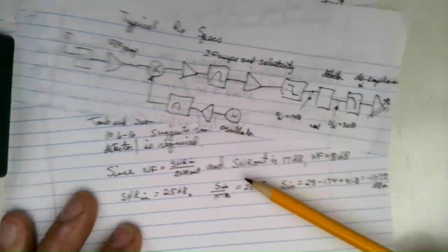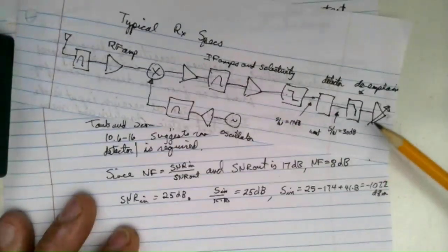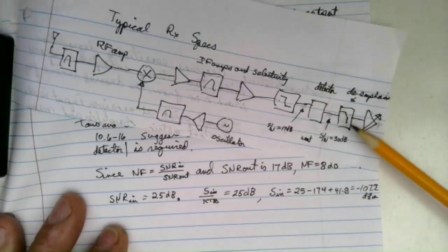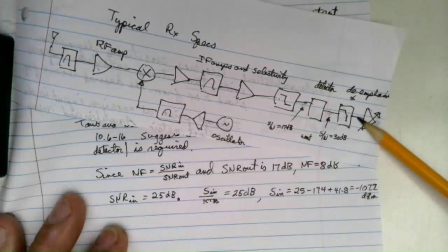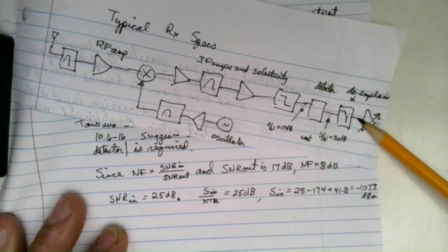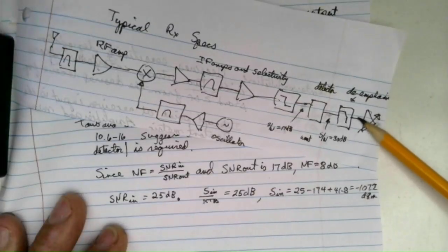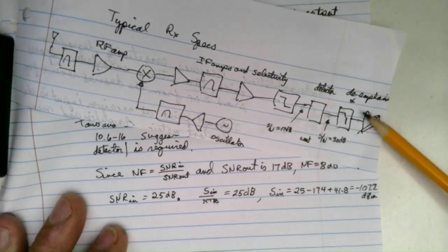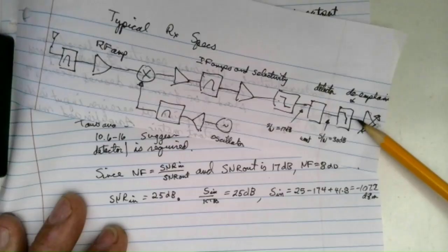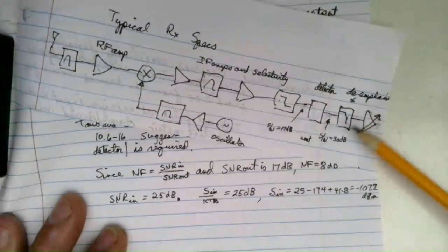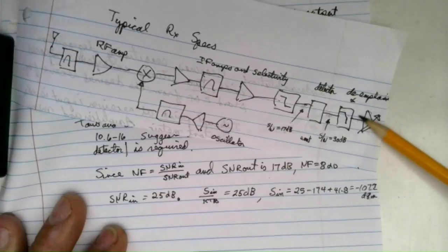By the way, there's a potential point of confusion: the bandwidth here is 15 kilohertz, because most people wouldn't express a low pass bandwidth as being double-sided. Even though it's really plus 15 kilohertz to minus 15 kilohertz, you might say that's 30 kilohertz. But most of the time you would describe a baseband bandwidth like that as from 0 to whatever the upper frequency limit is, not from minus 15 to plus 15, for instance. So you go from 0 to plus 15 kilohertz.